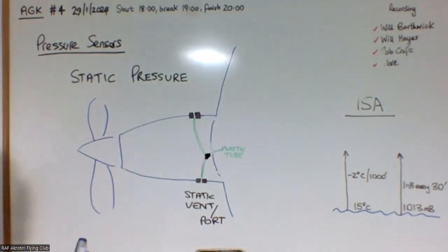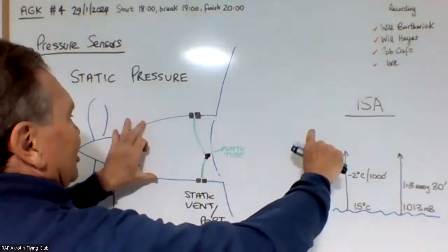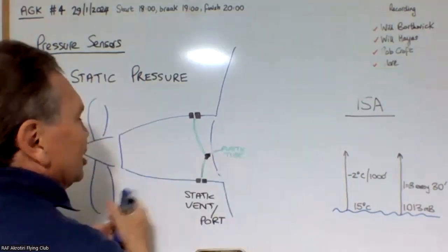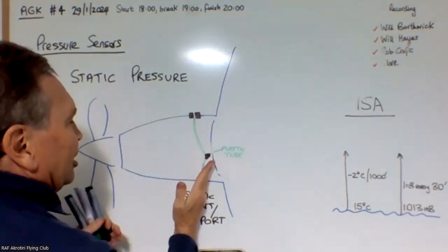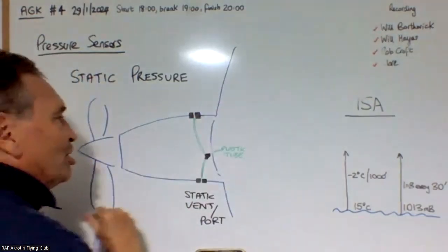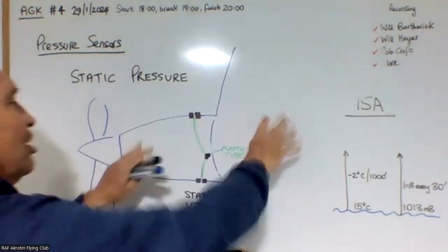That simply connects the tubes together. The idea being that if the plane is just flying slightly sideways, one of them would be having a slight suction and the other one was receiving slightly extra pressure, and the two would balance one another out.